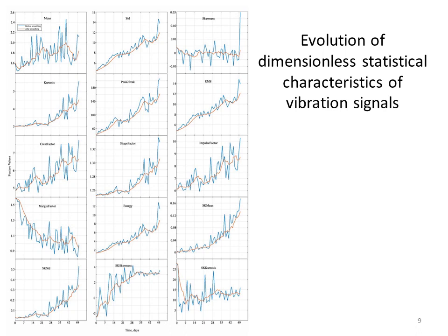In the frequency domain, 4 statistical characteristics were determined: spectral mean, SK mean, spectral standard deviation, SK-STD, spectral skewness, SK-skewness, and spectral kurtosis, SK-kurtosis. All the above statistical characteristics of the vibration signals can serve as potential indicators of bearing condition degradation.